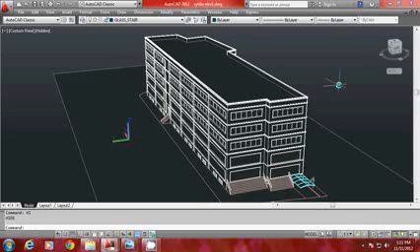So how do you make it? In a 3-point perspective, the camera and the target should be at different elevations, at different heights, and the line of sight should be inclined. So it is very easy to generate perspectives using Autocad software, and you have a lot of flexibility in controlling the position of the camera and certain parameters such as the focal length of the camera and the type of view, the type of perspective, etc.